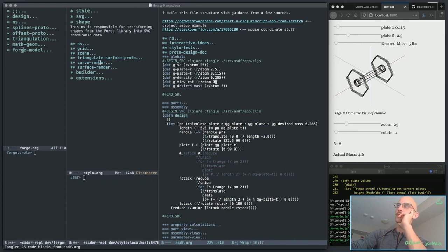In particular, I need an actual drawing file for this hex shape, and I just need to know the length of the tube to cut, right? Because manufacturing this is actually pretty straightforward. You need the total number of plates to cut. You need a plate template, which is always going to be a hexagon, so you only need to give a few dimensions. The tube size is fixed for this design, so that's always easy. You just need to know the length and the tube type that it is.